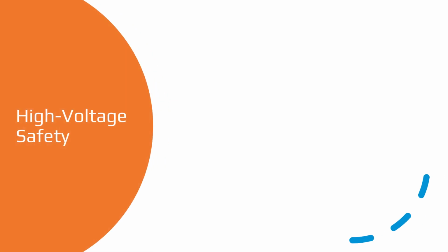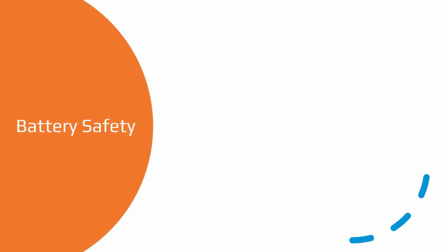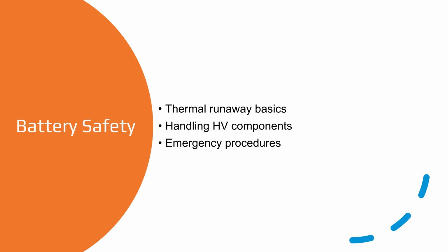Safety is paramount. This includes strict adherence to personal protective equipment requirements, proper use of service disconnects, and following established lockout/tagout procedures. Regarding battery safety, it is essential to understand the basics of thermal runaway, the correct procedures for handling high-voltage components, and emergency protocols.